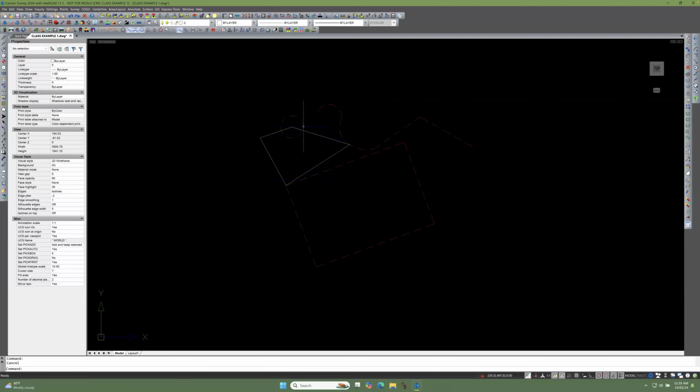Okay, so we're going to need to look at these things in 3 dimensions. And you can do it by this little trick, holding the shift key and pressing in the wheel and holding it and moving the mouse around. I'll reset that, go back to top view.